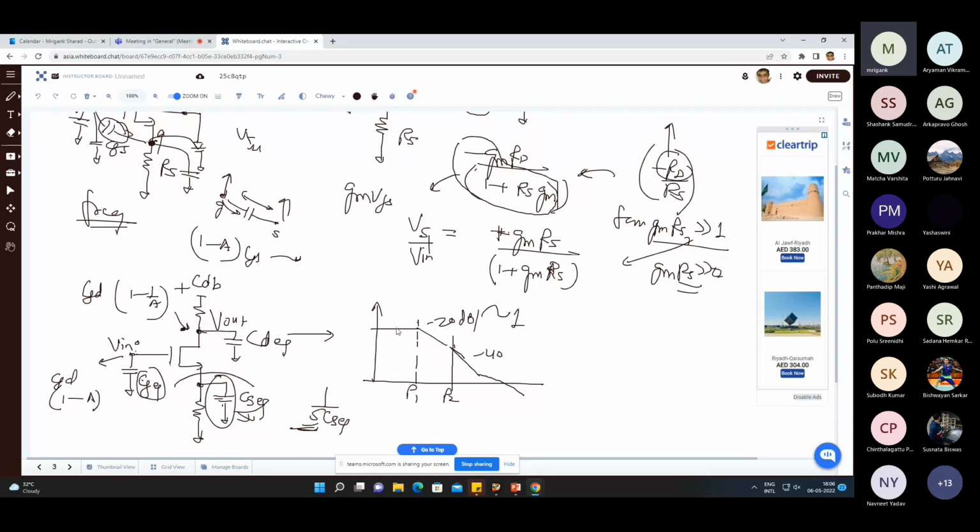Initially, it may degrade by minus 20 dB per decade, after that minus 30 dB per decade, and after that the slope may gradually increase back to minus 20 dB per decade. Again, it is just an approximation. The actual curve is going to be a smoother transition. But conceptually we can analyze the effect of each capacitance and which is the dominant pole.